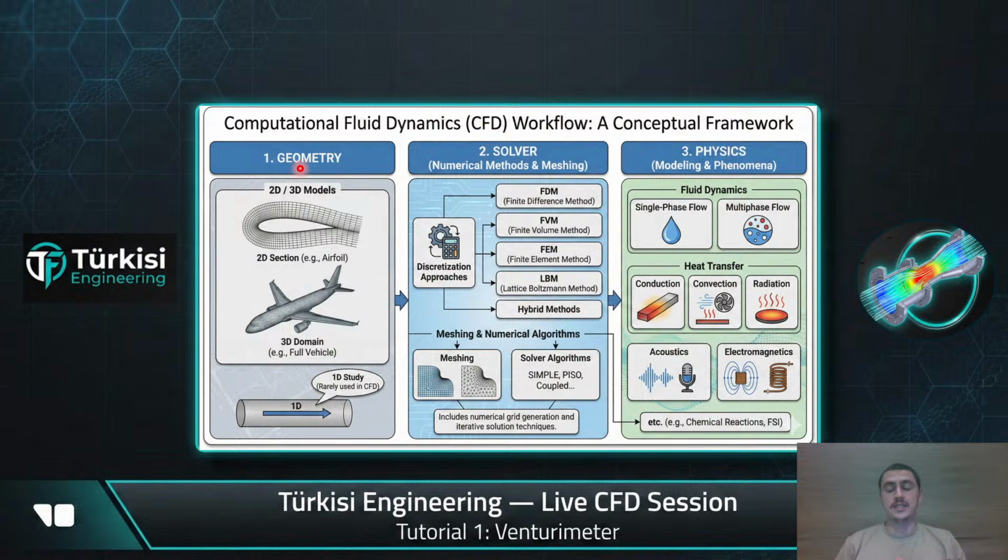We can extract a lot of useful information. So to simplify the geometry, the meshing, and our solution, and to simplify the computer's work, you can simplify your geometry to get a 2D solution. Let's say we have single phase flow, only air is flowing. You define your geometry: what is my domain? Sometimes you need an enclosure. For example, here you have a solid, which will be your wall.